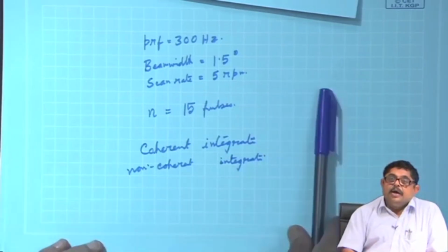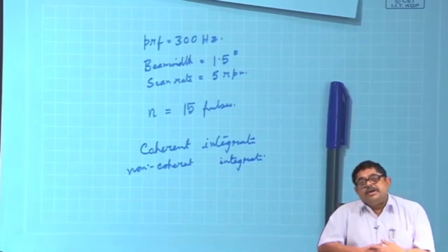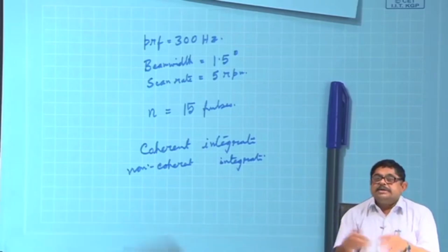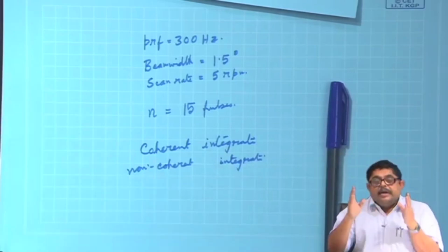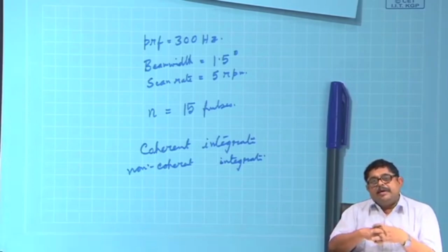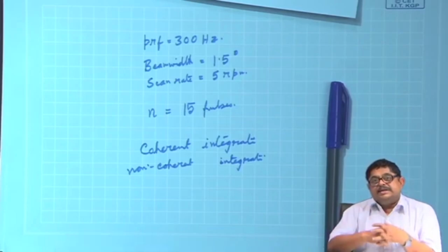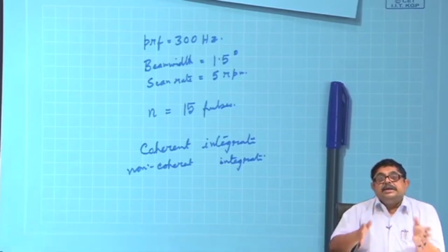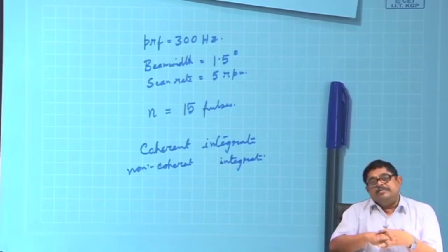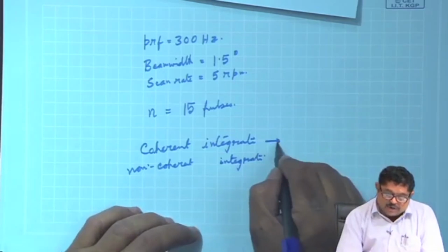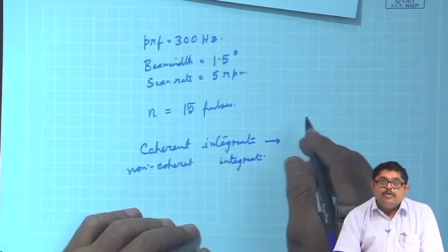Now, we have not discussed the radar receiver. Actually, a radar uses a superheterodyne receiver, so there are two detector stages. From the second detector of the IF stage, the signal phase is lost. So, this integration needs to be performed before the second detector of the receiver, and only then will you get coherent integration. That we will see later, but remember it, because at that time this will be recalled.